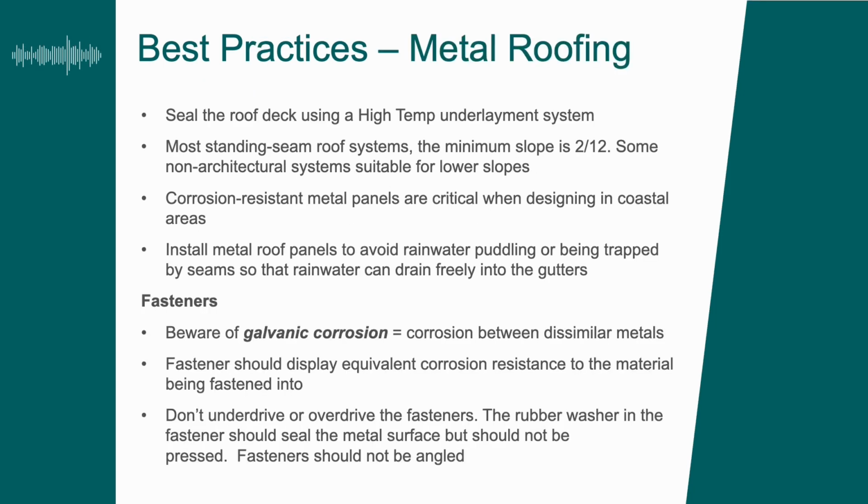For metal roofing, we also recommend sealing the roof deck but using a high-temp underlayment system, and we'll cover what high-temp means here in the next section. Most standing seam roof systems have minimum slopes of 2 and 12, so make sure that your underlayment and your roof system is adequate for that minimum slope.